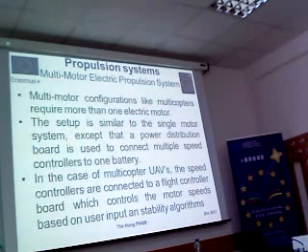And this algorithm influences some algorithms. For example, PID will use the linearized model, but in some other controllers, for example MPC, model predictive control, or LPV, linear parameter varying, they can use a non-linear model in order to control.